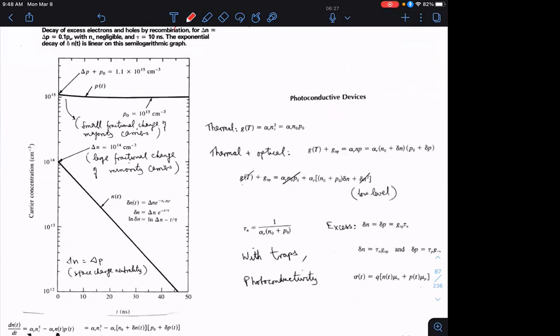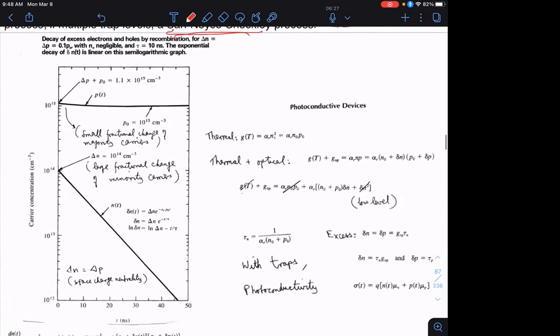All right. So what I'm doing next is essentially a worked out example that introduces some key concepts. The example I'm working out is a semiconductor which is doped p-type at 1 × 10^15. And on that, I'm shining laser light. So this is non-equilibrium. Laser light with h nu greater than the band gap, at a flux where I create excess electron-hole pairs.